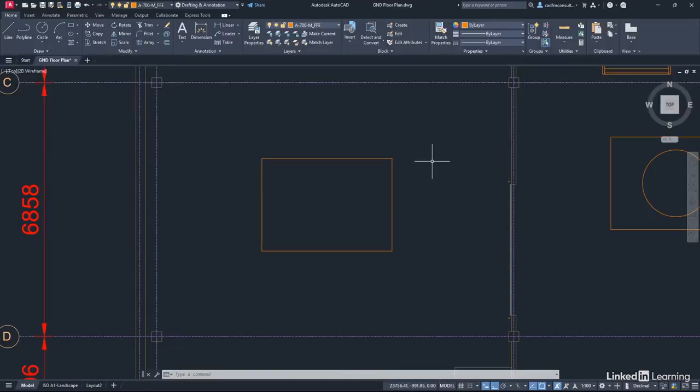Ortho is restrictive, and it's deliberately restrictive because it's tying you down to the X and Y axes. If you want a bit more freehand, turn the ortho off and put the polar tracking on, and use polar tracking to work with angle increments and individual angles. Depends on what you're drawing, depends on what environment you're drawing in, and so on and so forth. But that's utilizing polar and ortho to add geometry to your drawings.